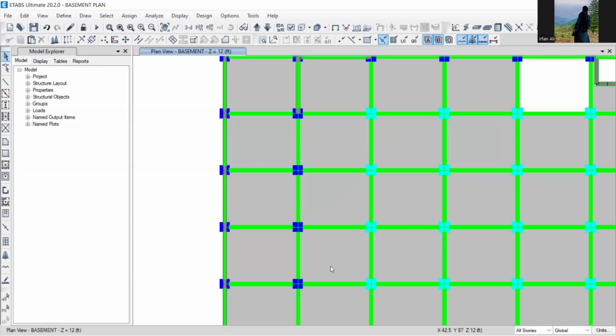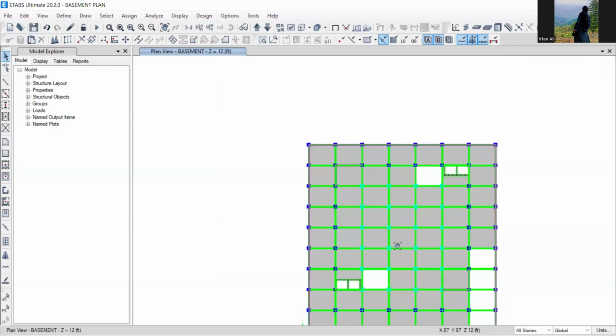Right, but the problem you will face in single story and 2 story is that the new code, the Building Code of Pakistan 2021, will apply too much force on very low rise buildings. So you can do it as a case study: you design a 20-story building and take the column size as 30x30 or 42x42, and you take a 3-story building and take the same sizes. The amount of reinforcement you are getting in the 20-story building will be less as compared to the 3-story building. So obviously it will be economical.